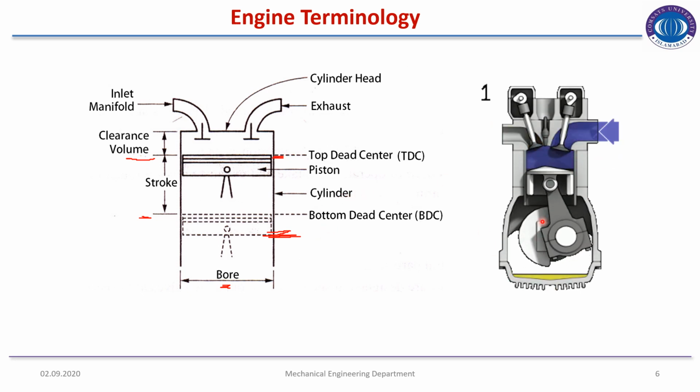So this is an animated diagram of this engine. As you can see there is a number going 1, 2, 3 and 4. So this means that it is a 4-stroke engine animation. So initially you will see when one, blue gas is entering into the cylinder. Piston is moving down, then piston is moving up. For compression there will be a spark, and after this compression there will be spark. So working fluid will expand, so it will force the piston to move down.